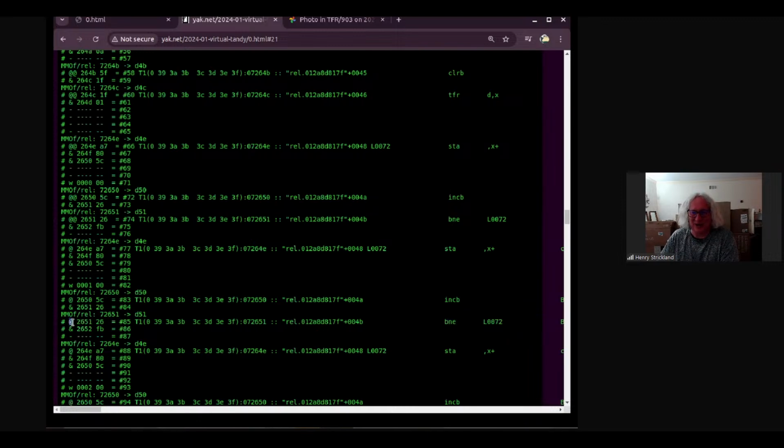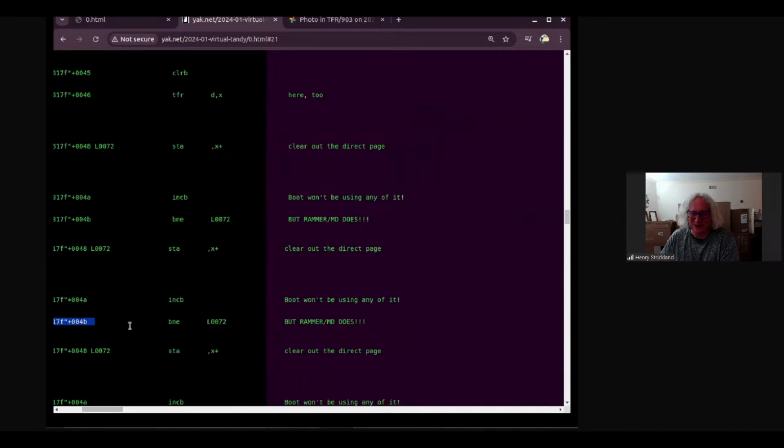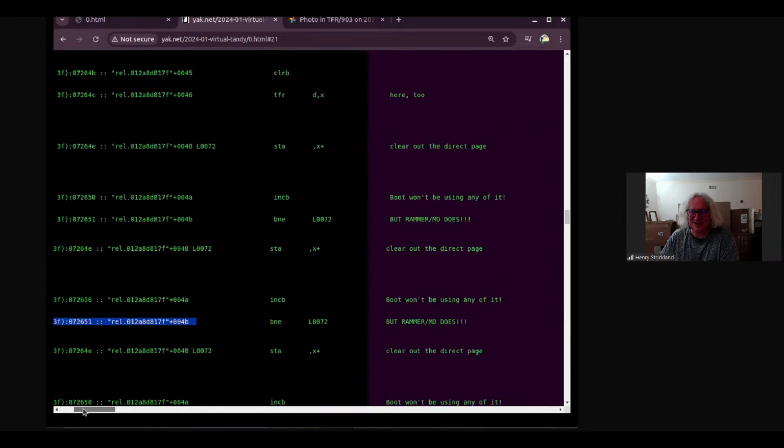And the way we know that it's the first opcode of an instruction is from the LIC line. The last instruction cycle was asserted during that previous cycle. And so we know that we can disassemble this instruction. We're actually not disassembling, we're lining it up with the listings from the assembler.